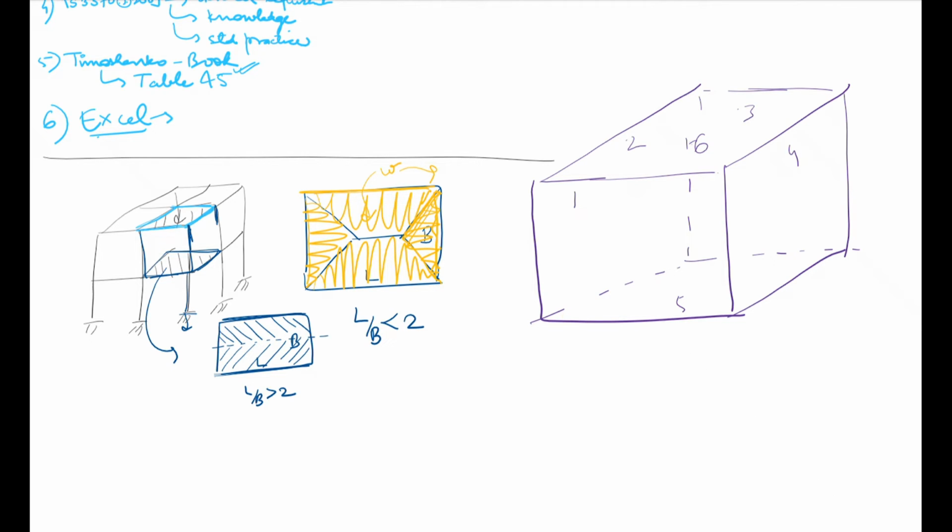So these slabs are connected directly to each other. There is no intermediate beam or column. There is no beam here. There is no beam here. There is no beam. No column here. These slabs are directly connected to each other. So there's a combined effect of all these slabs acting together. When there is a load acting on this face, this face will bend like this, right?